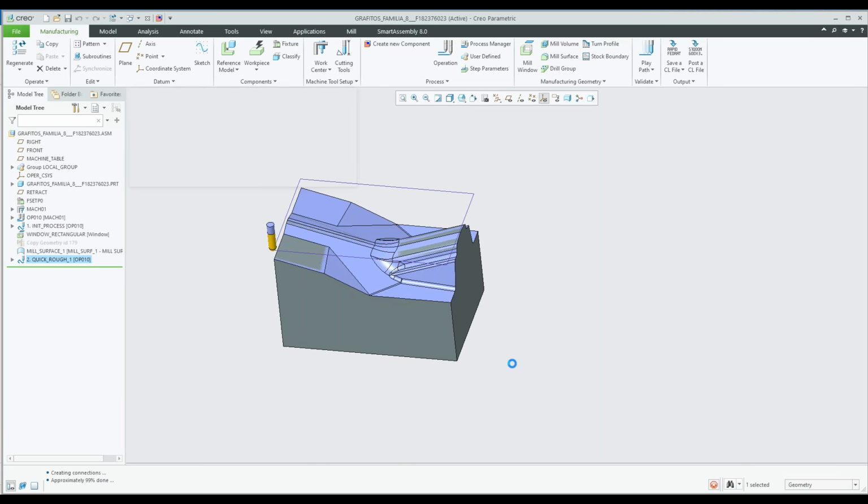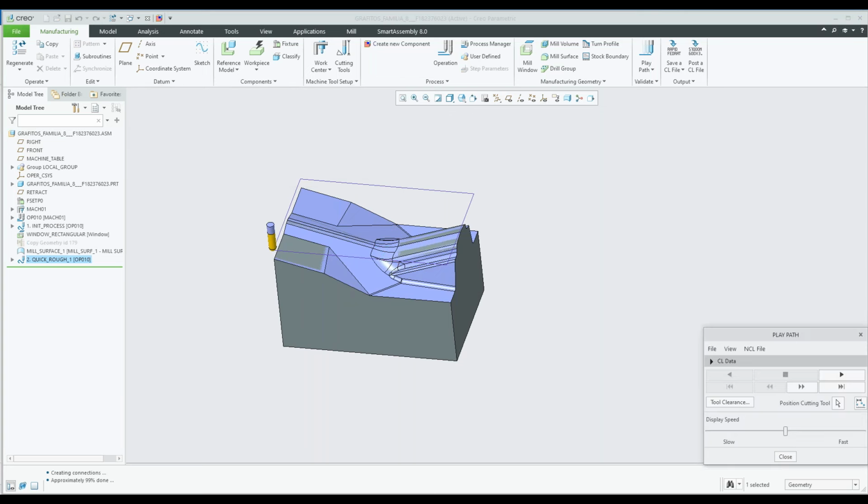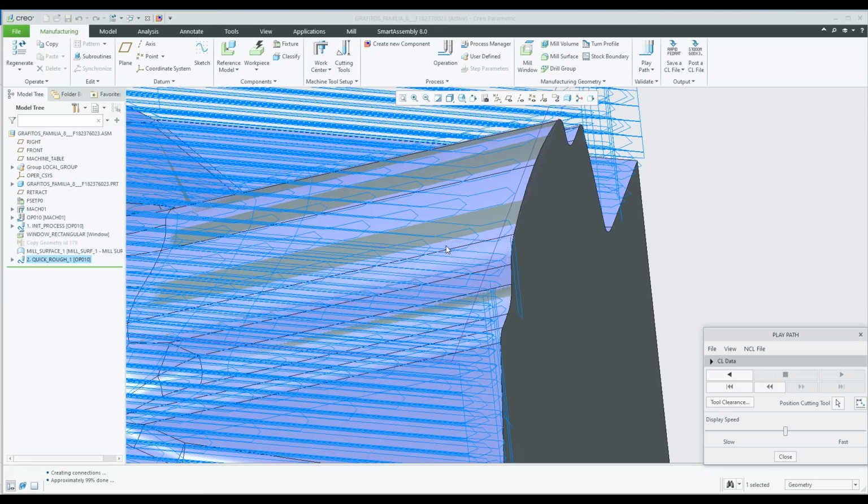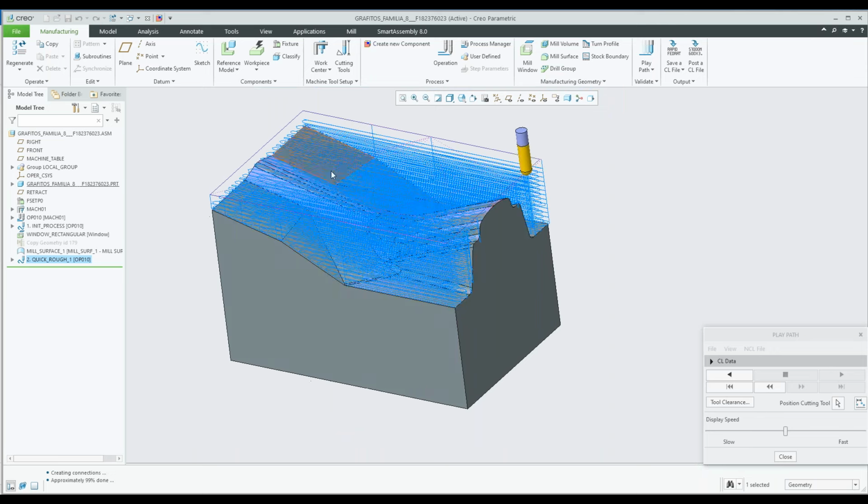I haven't set any parameters for any tooling. All of that was done previously, trial and tested: cutting speeds and feeds and cut depths. So I know this is right. I can put this on the machine with confidence. A new guy doesn't have to worry about cutting too fast or too slow or with the wrong cutters. Everything is there. And there's our tool path. That's just a roughing tool path with a big ball cutter.